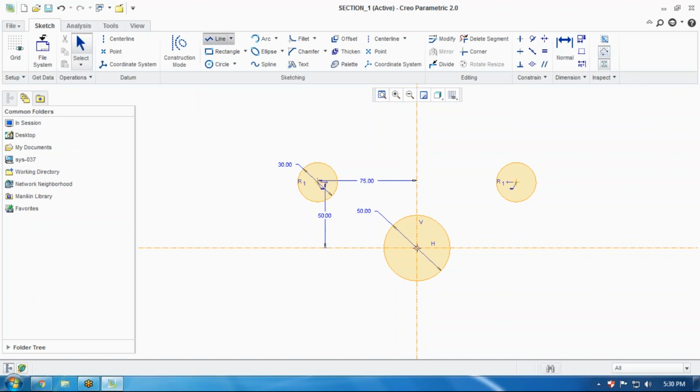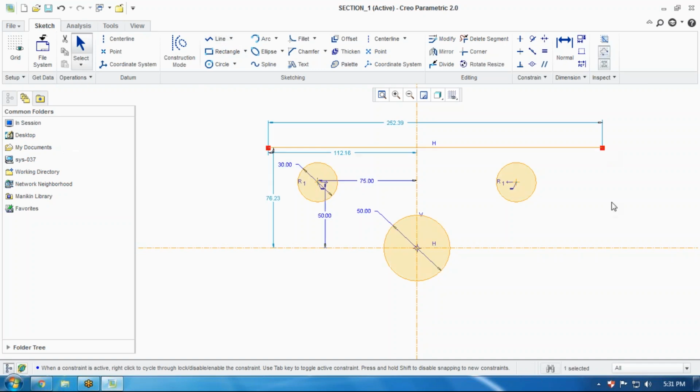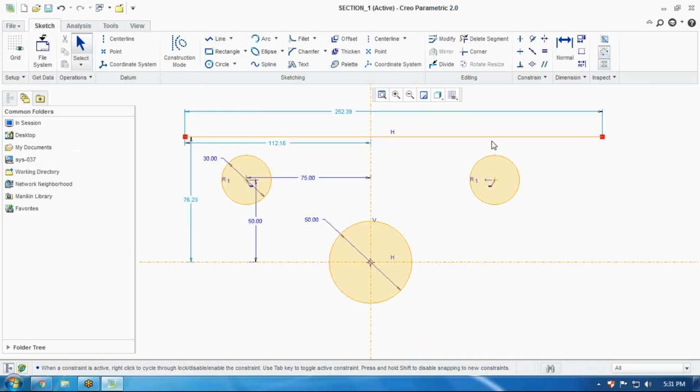If I'm just having a line segment here on the screen like this, and now you can see easily that they both are at some distance, right? But which one is stronger? You can easily see that this circle is in relationship with the vertical and horizontal line, and this circle is in relationship with this circle. So this is automatically getting stronger. Now what am I doing? I want to move this line to touch this line. That touch is called a tangential relationship.